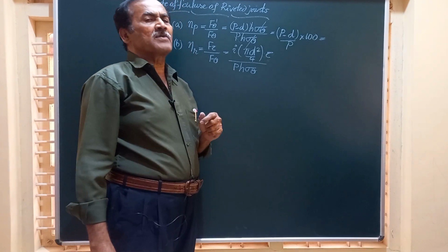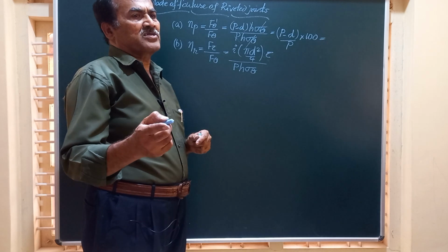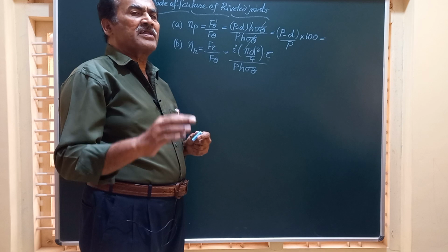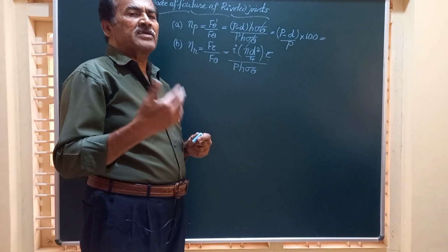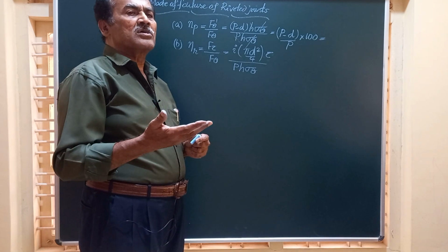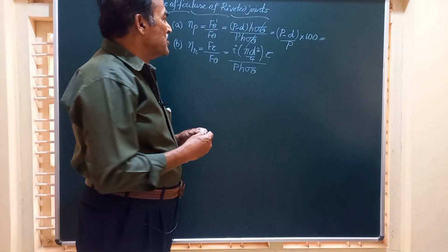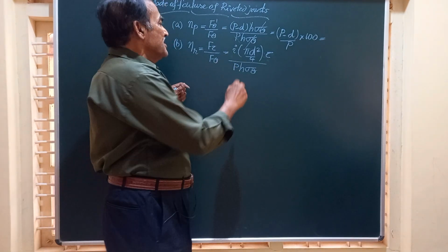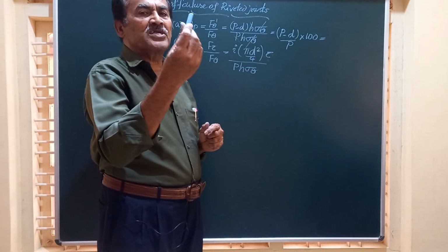And here we should know the meaning of each and every term. I stands for the total number of rivets. Remember friends, in any joint, there could be all the rivets failing by single shear, such as in the case of a lap joint, or all the rivets failing by double shear in the case of the riveted joint wherein you have got the two cover plates having the same width. So here I stands for the total number of rivets in that joint per pitch length. Pi d square by 4 means the area of cross section of each rivet.